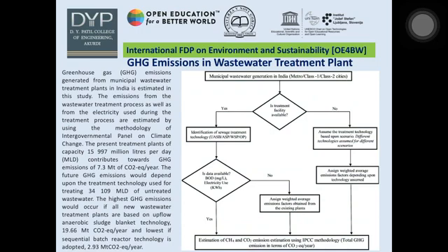In the picture you can see a pictorial representation or a flow chart constituting the municipal wastewater generation in India in metro, class 1 and class 2 cities. If treatment facilities are available, the identification of sewage treatment technology, UASB or ASP or WSP or OP, is to be taken into consideration. Then if data is available like BOD, electricity use, etc., then you can go for the estimation of CH4, that is methane, and CO2 emission estimation.